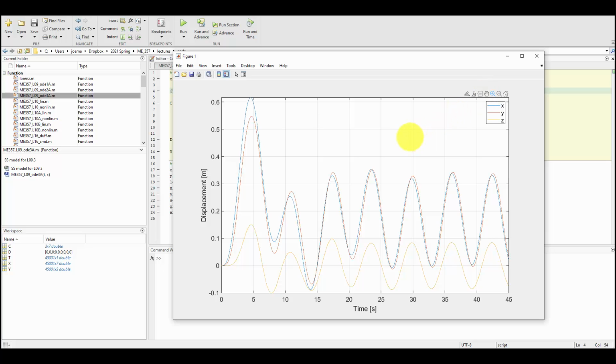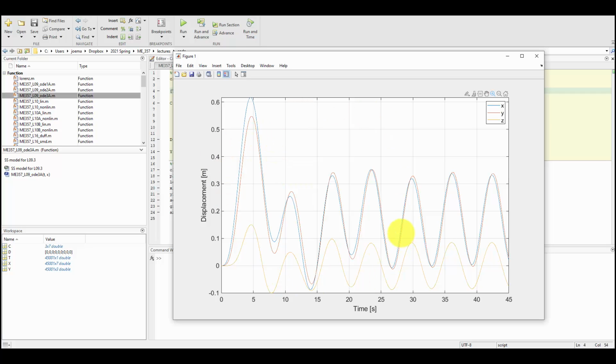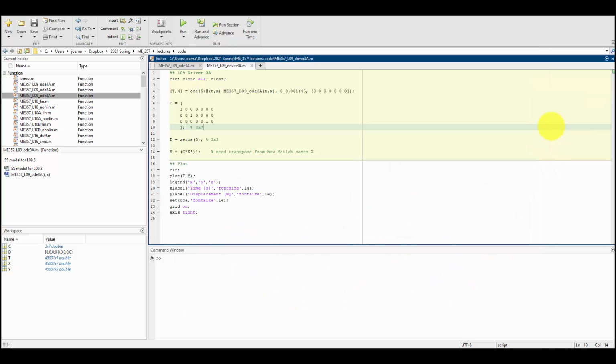And we'll again go into more depth as we go into Unit 2 here. But we see that the frequency appears the same for all 3 of our degrees of freedom. And that's going to happen when we have just that one sinusoidal input. However, they are slightly out of phase. Their peaks are not all lined up, and their amplitudes are different. This is exactly what's going to be expected for linear systems at what we call steady state, after those transients have died off around 30 seconds.